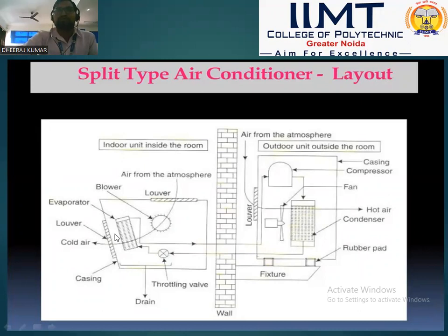The evaporator absorbs the heat inside the cabin and vaporizes. This process is repeated again, and saturated vapor refrigerant is again supplied into the compressor, and this cycle is repeated to maintain a constant temperature inside the cabin.